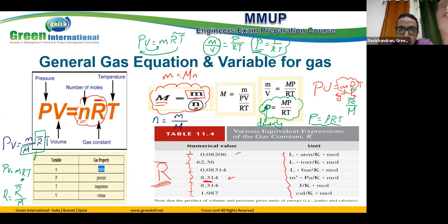So from this slide, we'll see PV equal nR bar T. R bar here is one value for all gases, a constant for gas. And the other equation, PV equal mRT, this one is used for a specific gas. And the last relation is P equal rho RT. Okay.